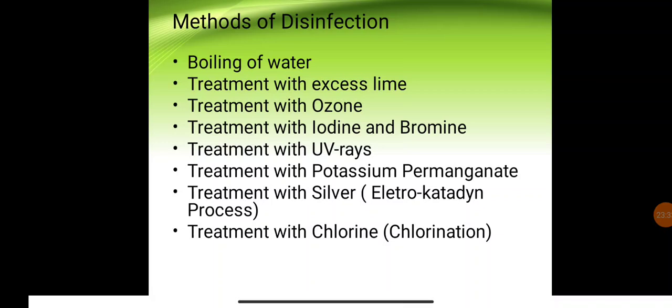When hypochlorous acid, HOCl, reacts with ammonia, it gives rise to the monochloramine. When it reacts with protein and amino acids, it gives rise to the dichloramine. When the hypochlorous acid reacts with phenol, it gives rise to the nitrogen trichloramine. The chloramines so formed are stable and are found to possess disinfectant properties.